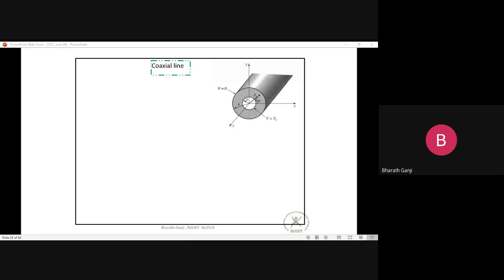because we know that a TEM wave has many advantages compared to a non-TEM one. A TEM wave does not have any dispersion. Its phase velocity is independent of the frequency. The pattern of the field is not going to change with frequency. And you can deal with voltage and currents if you're dealing with transverse electromagnetic waves, so we can even apply transmission line theory. So there are quite a few advantages if you're dealing with the TEM wave.